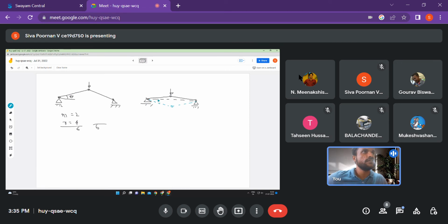So it's very similar to that, because here we are talking about 1D, but in 2D you can have surfaces. A dome, with very small curvature here, right? If you press on it, it will just buckle and become like a bowl, and once you leave it, it will again come back to the dome shape. So these are the things that will happen. It's happening because of the angle. If the angle was very steep, then it would not happen. Why is this happening? If you want to understand it mathematically, you can find out. If this is P, then if you do equilibrium, you will find out that the internal force is P by 2 sine theta.